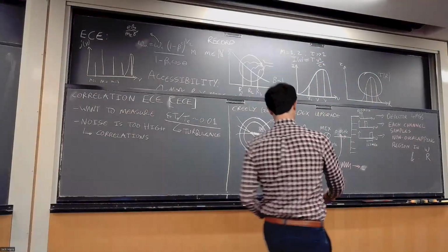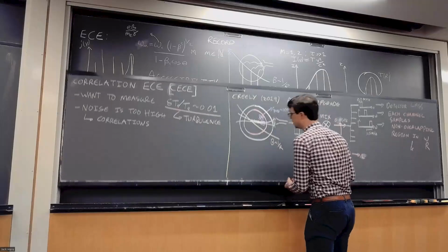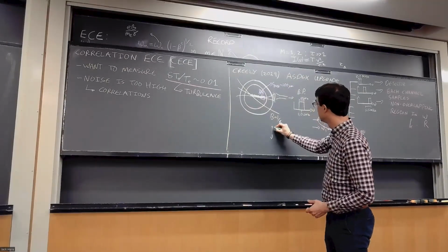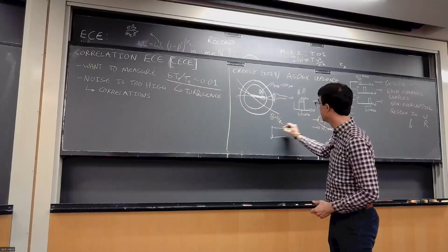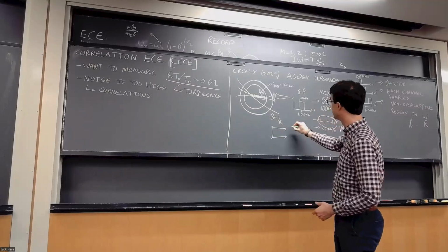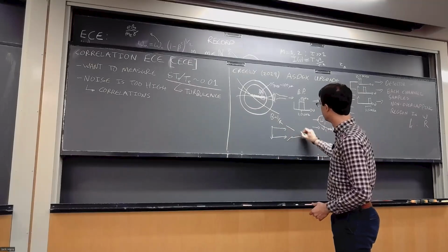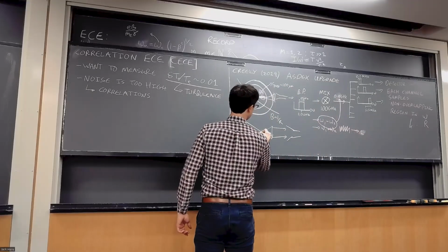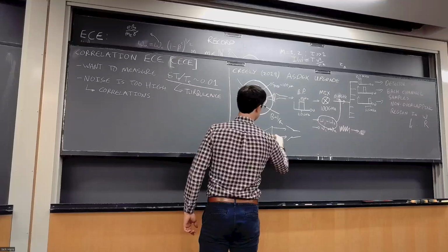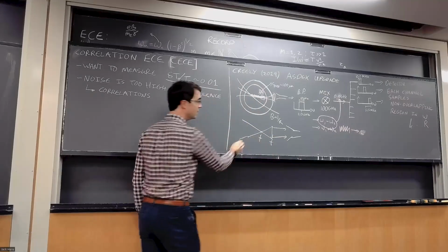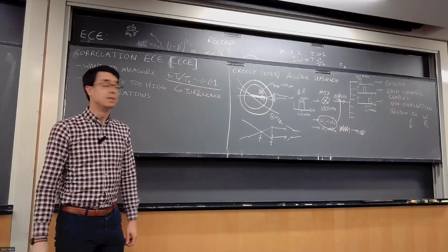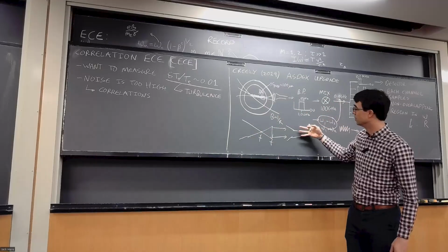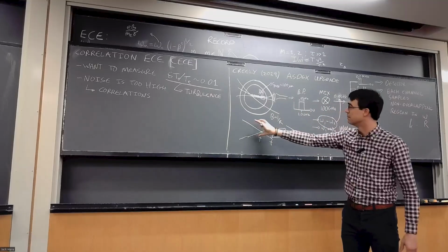So if we were doing geometric optics, which we're not, then you would have a lens like this. That lens could collimate your beam, as in we'd have a load of rays coming out into our horn. If it collimated that beam, there would be a focal point at some distance f away, if this lens has a focal length f, and then it will diverge afterwards. Because of reciprocity, as opposed to launching rays this way and seeing where they focus, we have rays coming from this way.